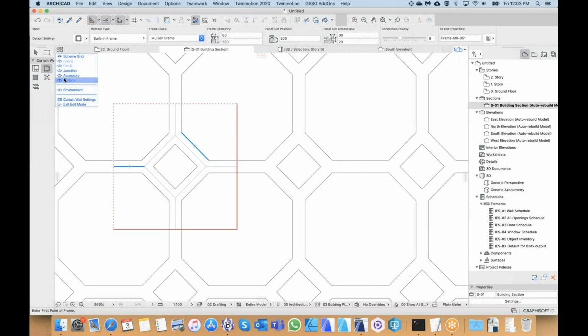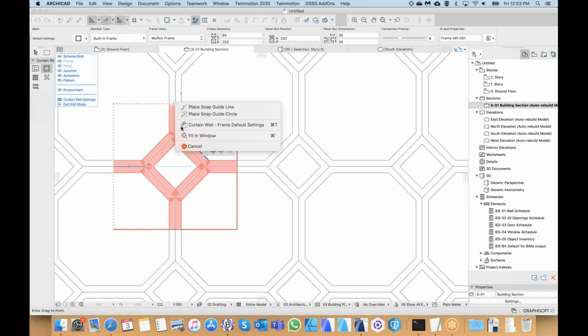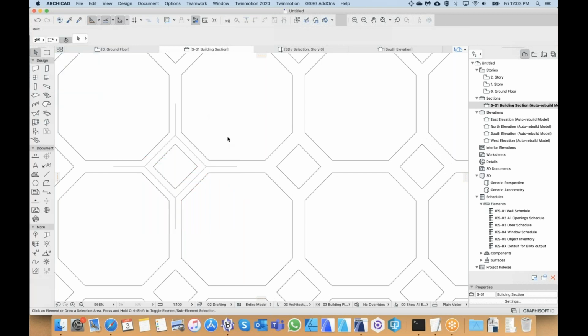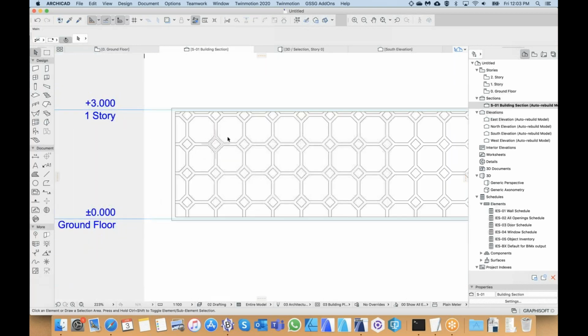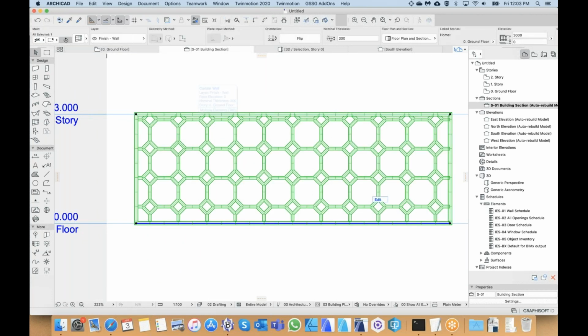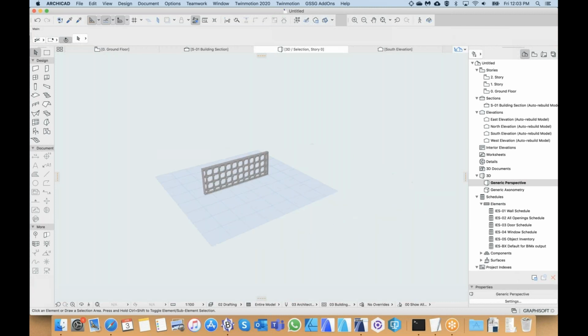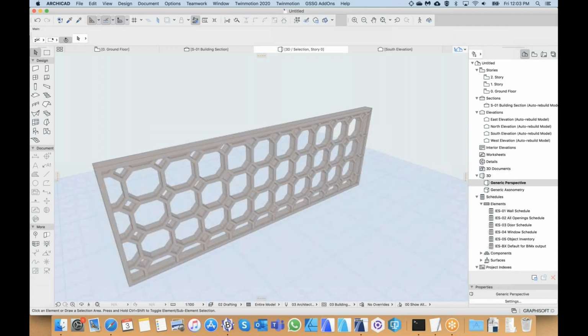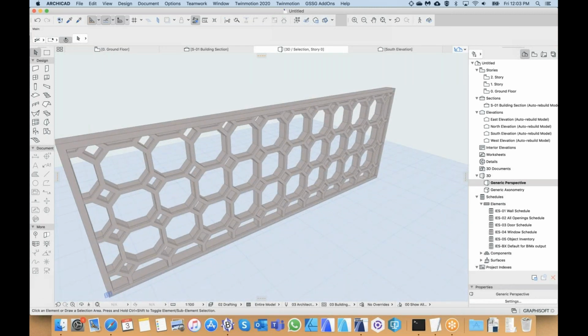Once we've got this pattern box on, we modify the boundary of the pattern to the ends of the frame, and once we've set it, we hit apply. Once it looks good, we exit from edit mode. Once I've exited, I select it and show this in 3D, F5. Now I can see my pattern repeated.